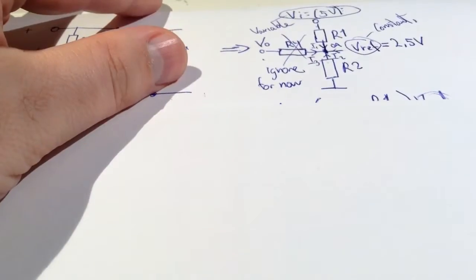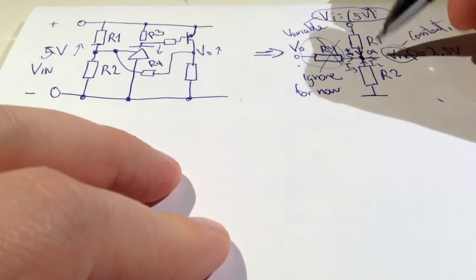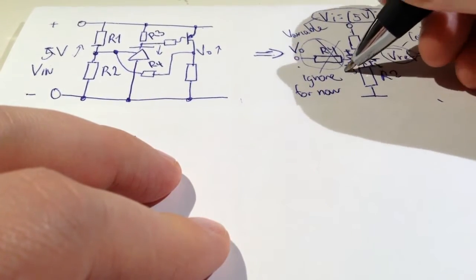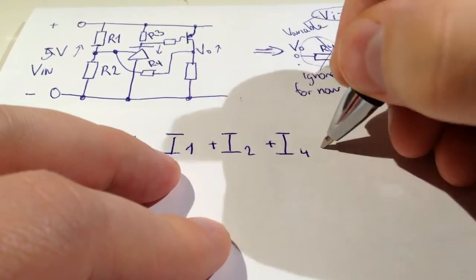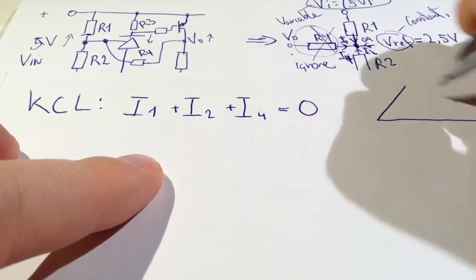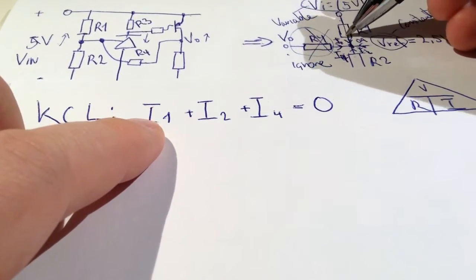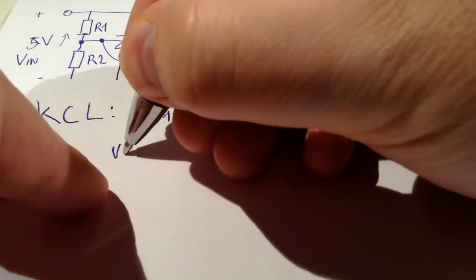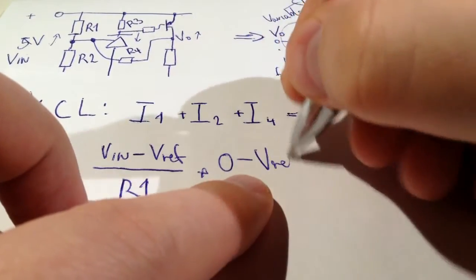So here's the part that I left out because I used the Kirchhoff current law, and it wasn't strictly necessary here because we could simply parallel the two resistors. But if for some reason V out is not going completely to 0 or up to 5 volt, the power supply voltage, let's say it only goes down to 2 volt because of that TL431, then you have to include it and you have a more complicated formula.